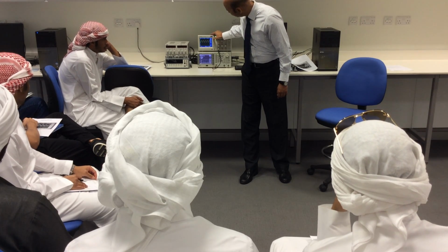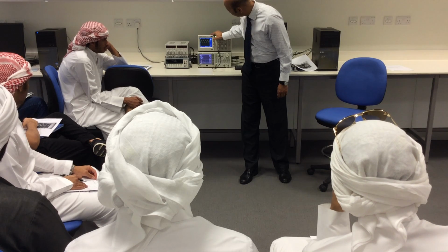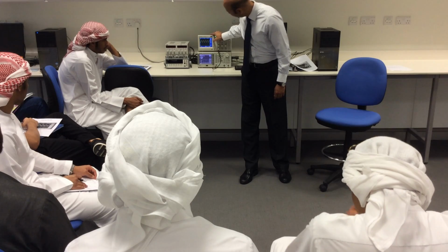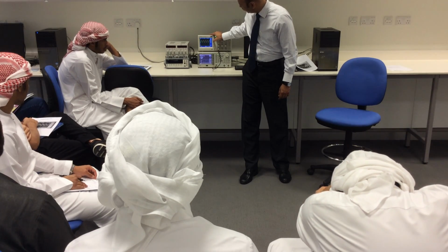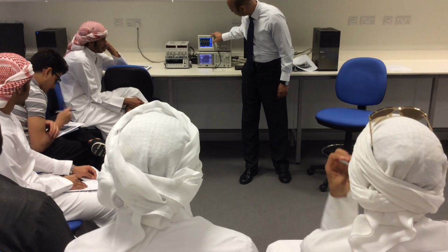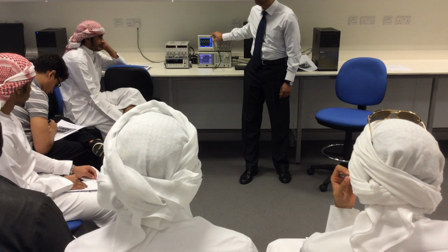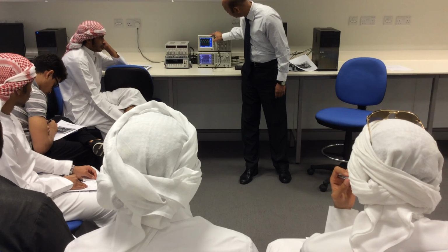And so here it is, channel 1. This is the value. And if you want to measure the period, this way, here it is. This is 10 millisecond. Right? 10 millisecond is the period. And if you want to measure some other thing, you keep pressing.